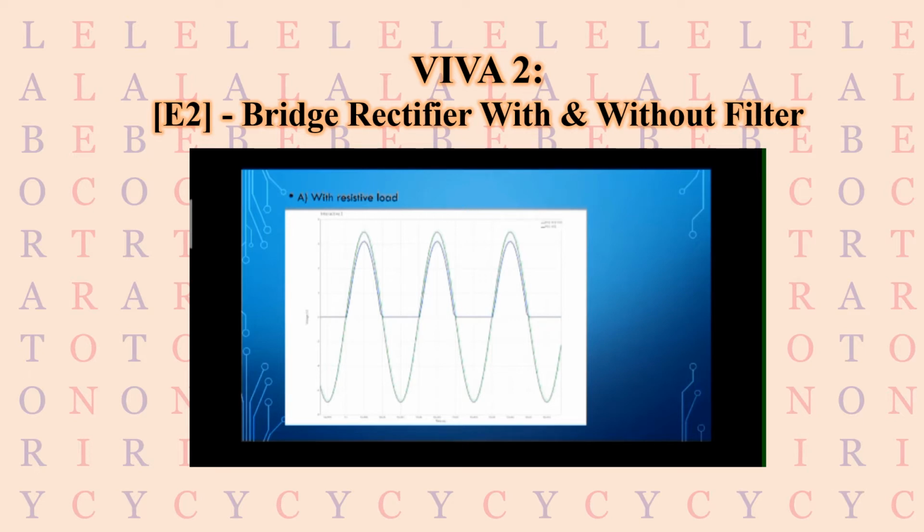When passing through the diode, it only allows one direction of flowing current. At the positive part of half cycle, the diode is turned on, which allows the current passing through load resistor. Thus, the load voltage will follow the positive half sine wave. However, the diode is turned off during the negative half cycle and blocks the current. Hence, there is no voltage during negative part half cycle.